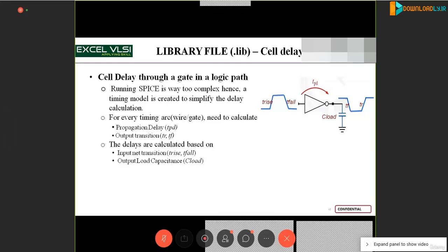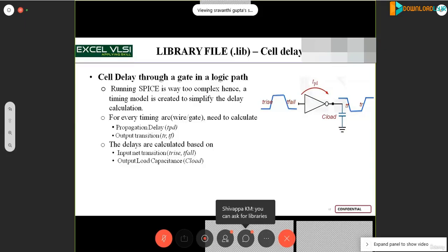It was way too difficult calculating with the SPICE level netlist model and depicting the timing values of each and every cell. So they moved to these timing models, where the delay values of each and every cell are already declared, and you can just interpolate and pick the value you want for the optimization of the timing, power, and area of your netlist.